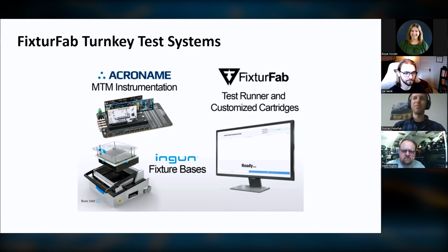One other thing that might be what they're asking is what they call double stage probing. This is typically used when you try to integrate in-circuit testing as well as functional testing within the same fixture base. With this, you'll have two different heights that the device will be set at, and the idea is you can use probes with different lengths. When it's all the way down in the fixture, every single probe will make contact, and that's where you'll do your in-circuit testing. And then for functional testing, you only need half that many probes, so you'll have it raise up and only the longer probes will make contact.